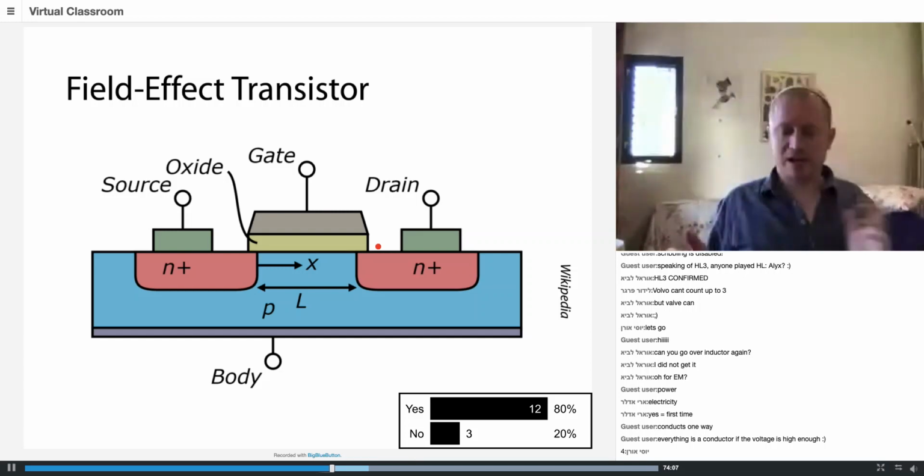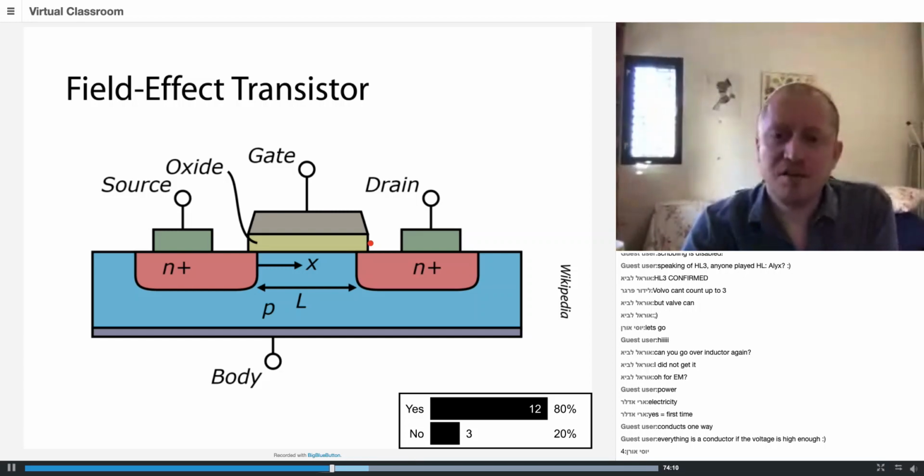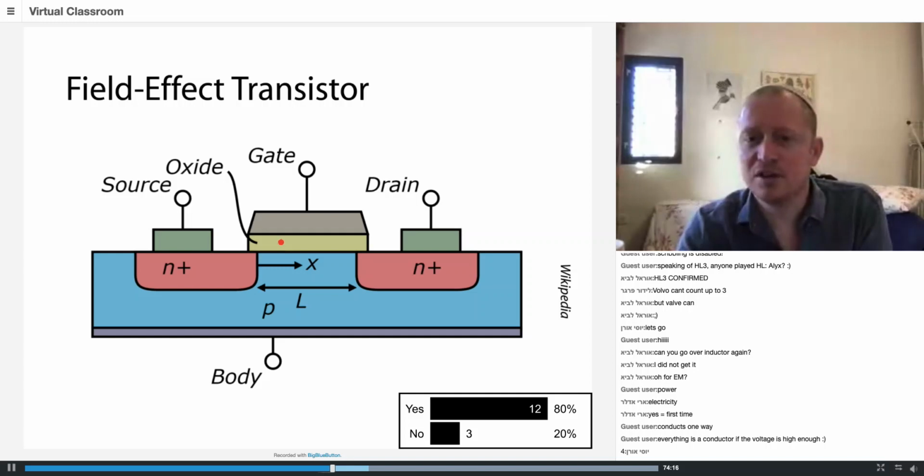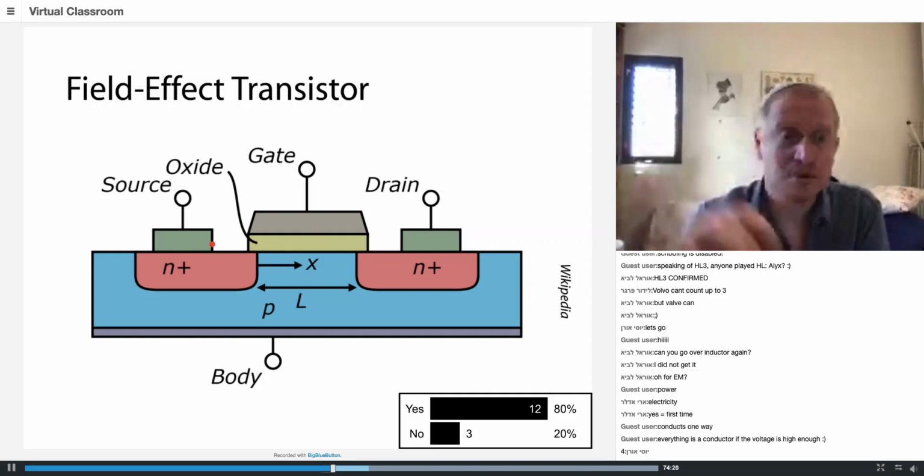What do you do in a MOSFET device? What you have here is an electrode. This is this brown thing, and this electrode isn't actually touching the silicon. There is a bit of glass insulator here. Silicon oxide is glass, now you know.